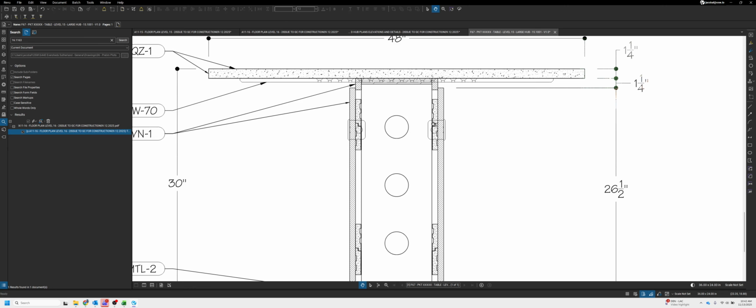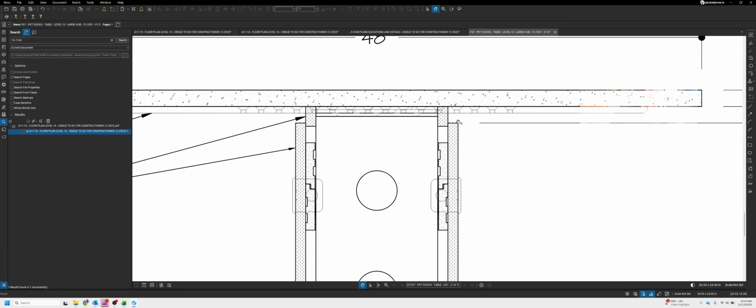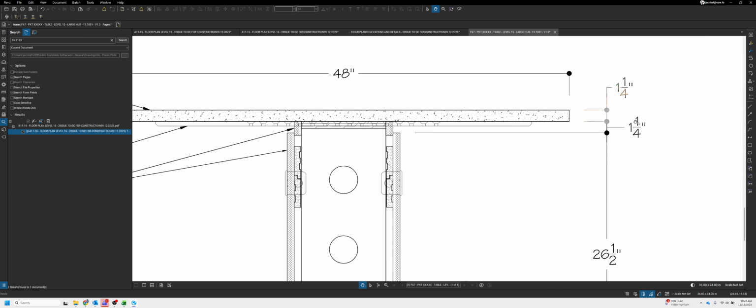I would say one thing to always take note of is anytime you have a bracket that hangs down below your counter like what we have here, and you have a panel that's removable below it, always be mindful that no matter what, you need 3/4 of an inch lift-off space for these panel cleats to be able to work. So right now, my dimension for my reveal is 1.25 inches. The reason for that is this bracket is 1/2 inch thick, plus I have my 3/4 inch lift-off space. So I have a 1.25 inch reveal technically whenever there's not a bracket.